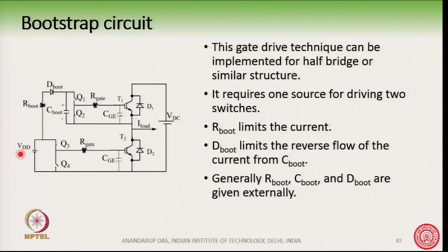Now we will talk about bootstrap circuits. Often, for this kind of voltage source converter, we drive half bridges, and we have seen that we can use gate driver boards for each IGBT: one driver for the high side IGBT, another driver for the low side IGBT.